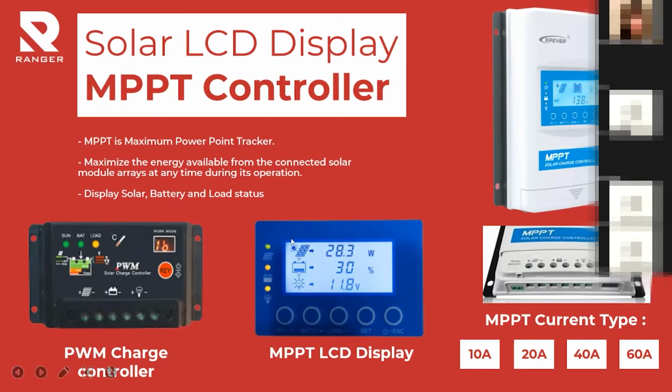This LCD display MPPT has another advantage, which is that the user can monitor the status of the battery. As you can see here, this is the status of the battery, solar, and load. The user can press the button here, for example this PV button for solar. When the user presses this button, they can see the watt, the current, and the voltage in. So it is better to use this MPPT LCD display because you can monitor.